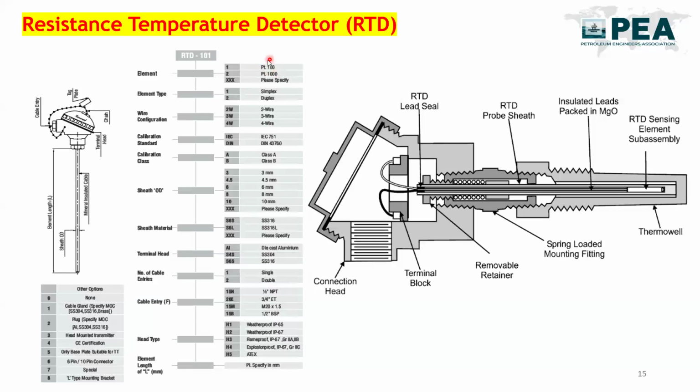Keep it in your mind, because you will always face this point in your working life or working culture, or in an interview also. Like the interviewer asks what you mean by PT100, or what kind of sensor we use for the RTD. So generally we use the PT100, that will show you 100 ohm resistance at 0 degree Celsius. As the temperature increases, the resistance will also increase.